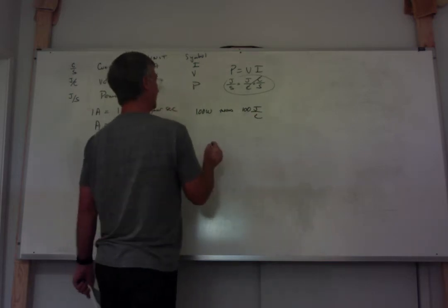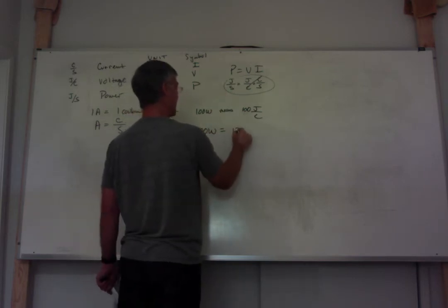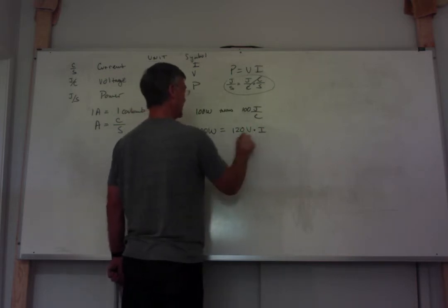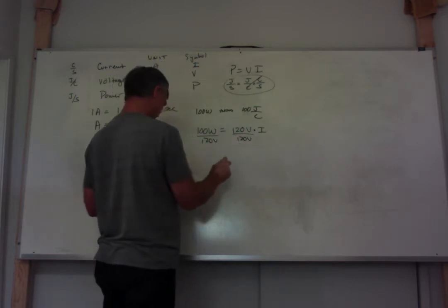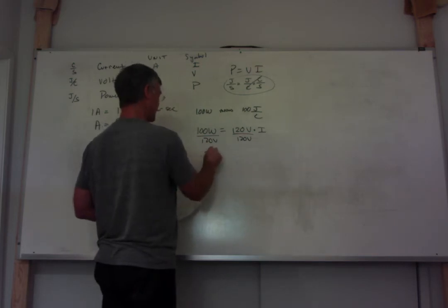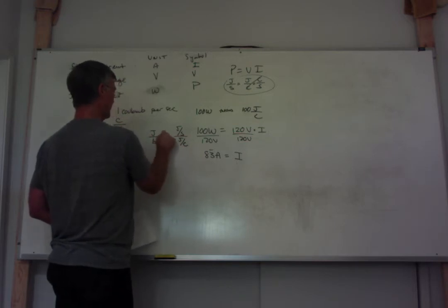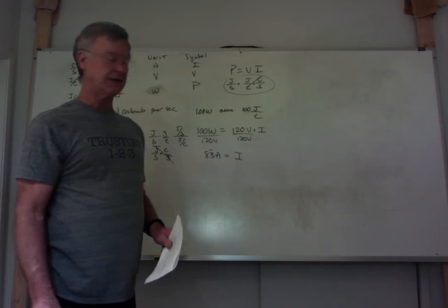Right? But if I had a 100 watt light bulb and I had 120 volts, which by the way is what your household voltage is, I can actually divide that, and this will be some of the problems that you do, and you will find that you have 0.83 amps is the amount of current. Remember, this is joules per second divided by joules per Coulomb, and when you redo that, you're going to get joules per second times coulombs per joule, 0.83 coulombs every single second.